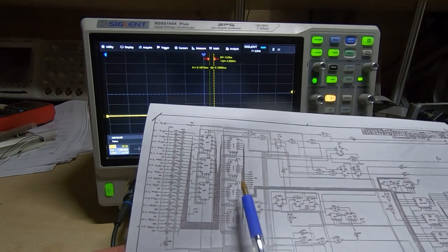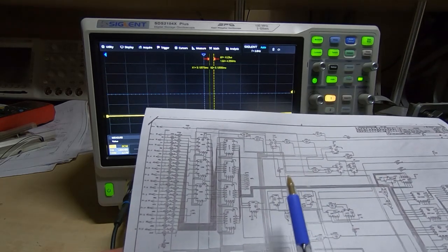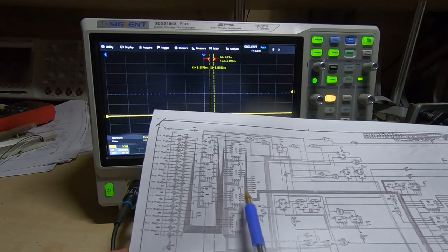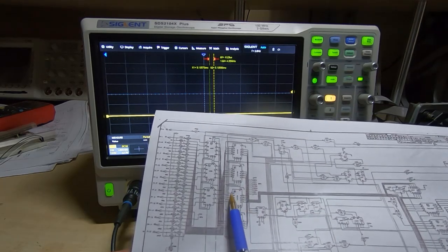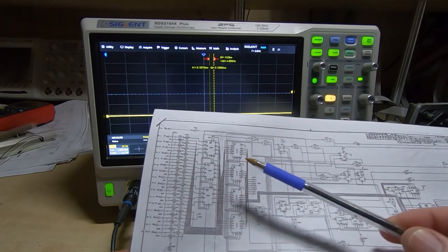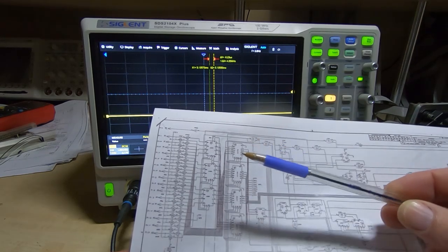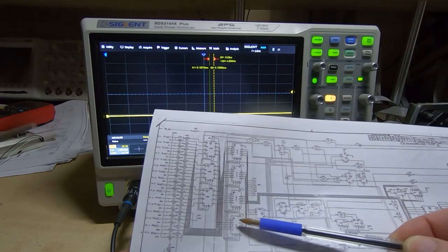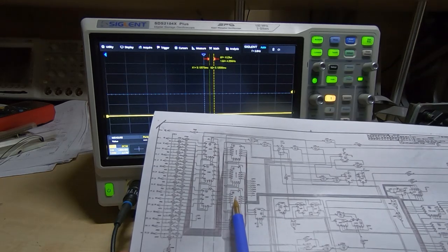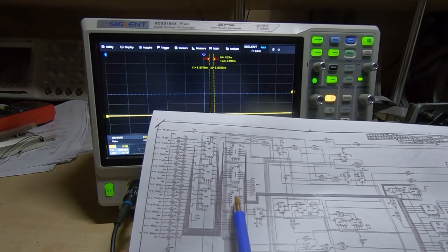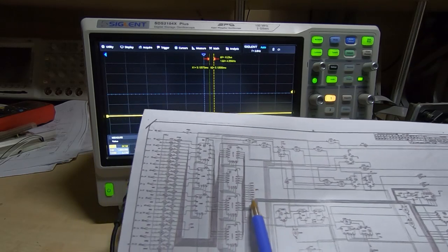One other thing I like to do when I'm working on systems like this is try and speculate as to where I think particular faults are. Now, I think there are at least 2 faults on this, but my money is on this particular IC, and the reason I think it's this one is because we know, roughly speaking, where the bit error is in the data that we're seeing. We know which of the devices is responsible for handling that bit, and so this device is responsible for latching the data that is being used as part of the control.